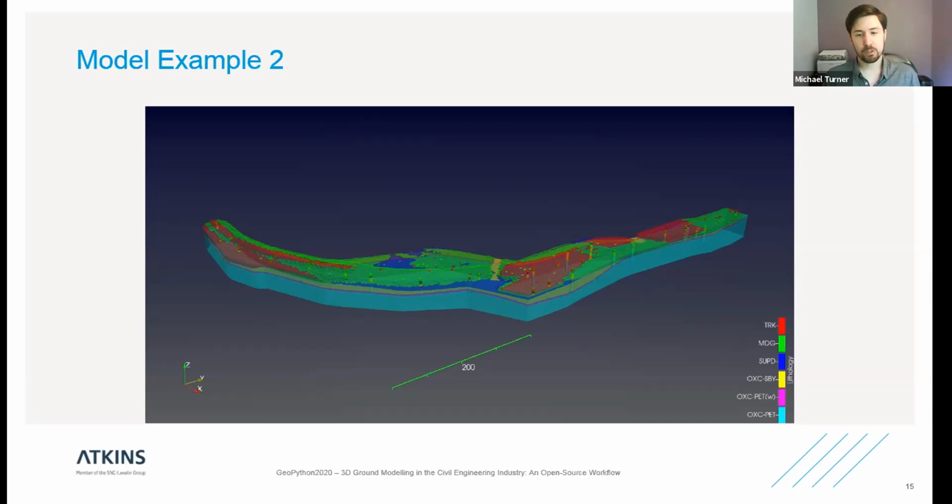Some potential directions this could possibly take is perhaps direct editing of the voxels in a block model like this, which could work quite nicely. Or alternatively, you could add additional manual control points, perhaps through some facility for the user to interpret cross sections or aerial extents of different strata. Now, obviously, if you do that, you don't want to change the raw data or to mix the raw data in with the control points. So you have to build a more complete system for handling those additional control points and tracking them separately to the main data set.